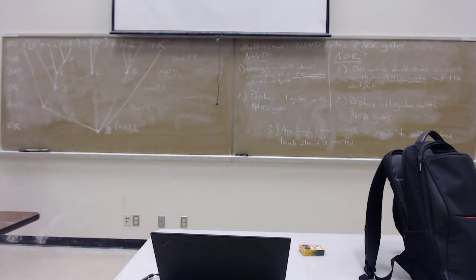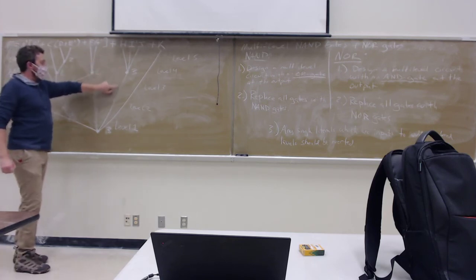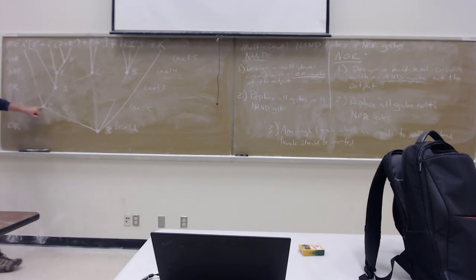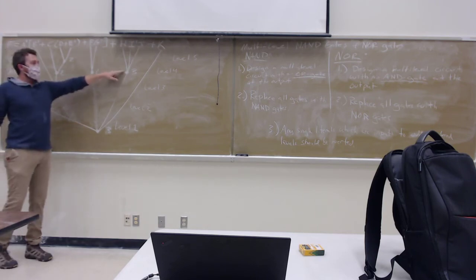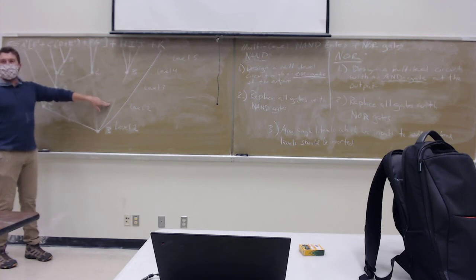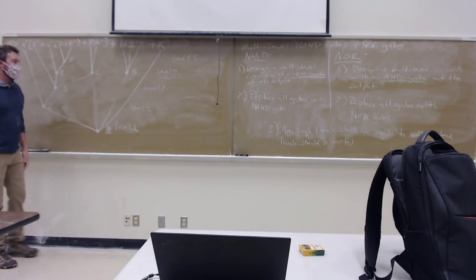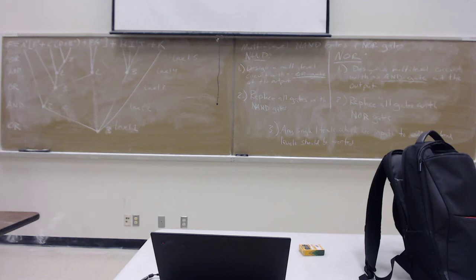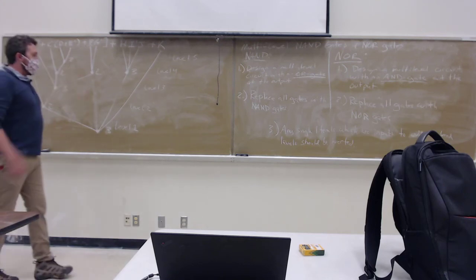I asked earlier, would it have mattered if we had done this AND operation here or here? And it really wouldn't have mattered either, right? Because in both cases they were even levels, so it wouldn't even have caused the inputs to be inverted. Maybe when you're laying out the circuit, there might be a reason to scoot him down to level 2 to make room for something else.